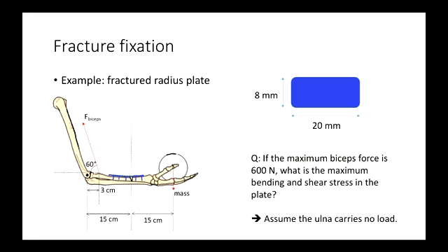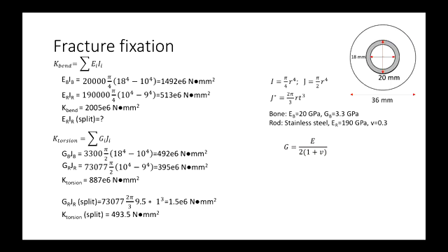Sorry, I have a question. For the one up above with the 2 cylinders, one inside the other. For the modulus times inertia, why is that 18 multiplied by 2 to the 4 minus 2 to the 4? So what's that formula? For a circle, I equals pi on 4 times r to the 4, right?